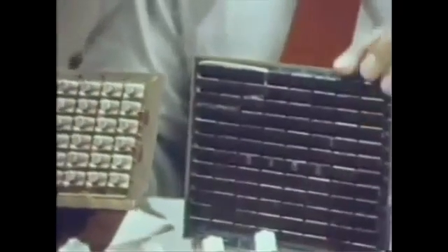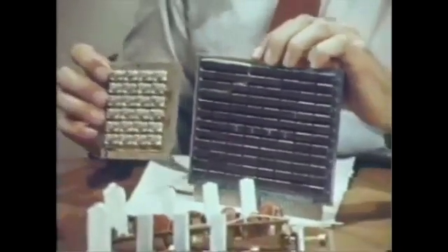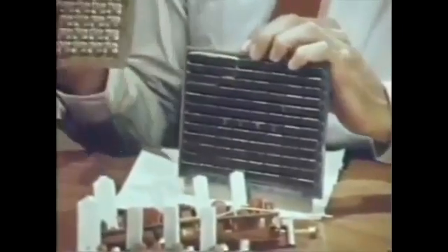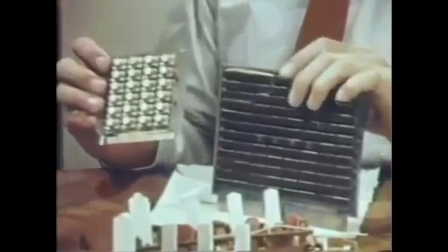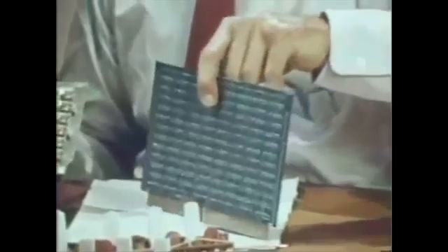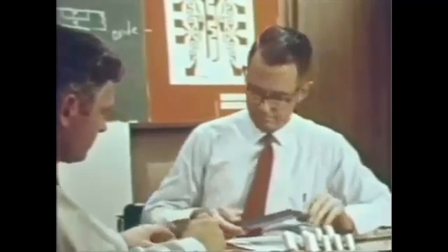I have here a newer version of integrated circuits containing in the upper left-hand corner 8 integrated circuits outlined. Now those 8 integrated circuits provide essentially the same function that was provided by this board, namely 24 integrated circuits down to 8. Notice that the wiring on this package is extremely orderly and well organized. I see less pin connections, too. This is perhaps typical, Harry, that we find as we make a more complex function in one structure, the number of pins tends to go up only as roughly the square root of the complexity that's provided by that board.